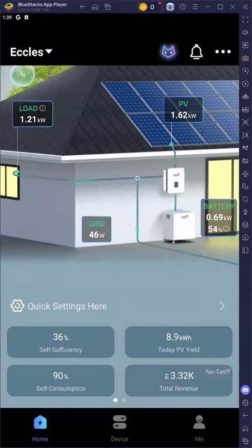Some of these settings are dependent on your inverter model, the hardware that is available, but also the inverter's firmware version. So if I cover something that's not available or you don't see the same settings, it's normally down to only a couple of things. Does your hardware support it? Is your firmware up to date? And is it restricted by something to do with your country settings? So certain features are only available in certain countries.